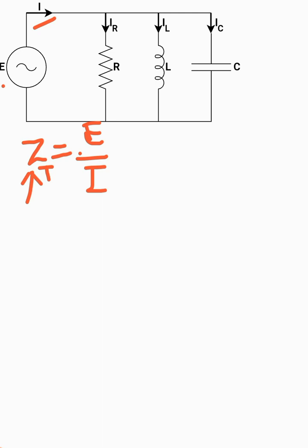Why? Because the circuit contains, along with the resistors, inductors and capacitors as well, which offer their own reactances. Just like a resistor has resistance, the inductance and capacitance have their reactances. So the equivalent resistance of the circuit will be termed as equivalent impedance of the circuit. And that ZT can be calculated as the ratio of voltage divided by the total current.